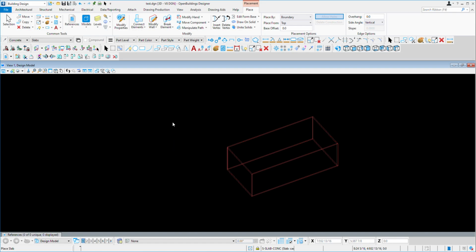It can be changed as per your project requirement and whatever library you have in your project. Thickness you can select. My slab thickness is 0.1, and it is one way direction. The reinforcement angle you can select here, but it is not required for 3D modeling. Okay, then let's start.